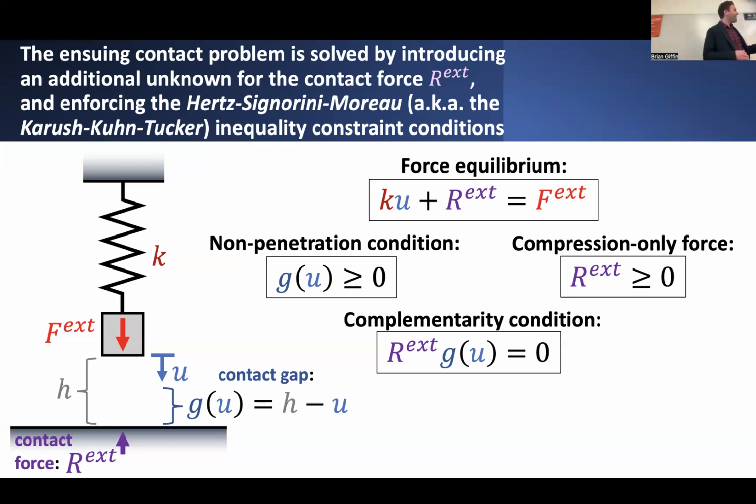And that just can't happen if there's no adhesive properties to that interface. If there's really nothing that should hold these two surfaces together, then once we remove that contact constraint from being enforced, this force should just go back to 0.